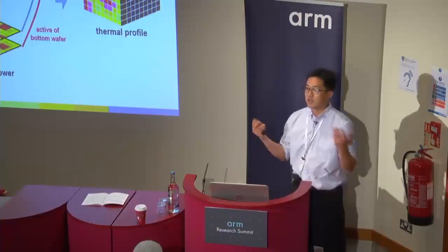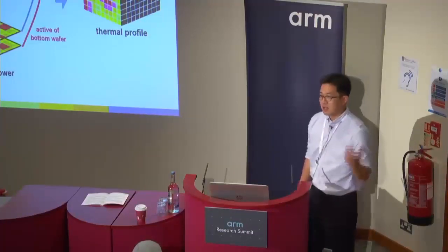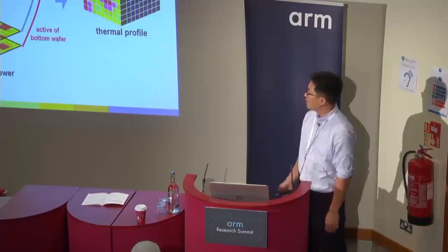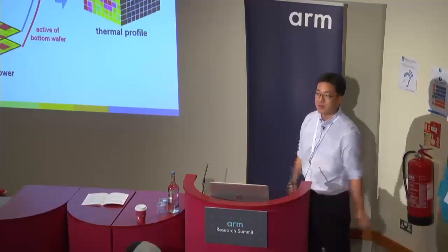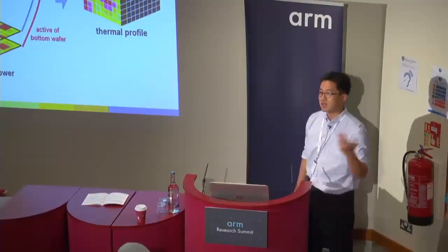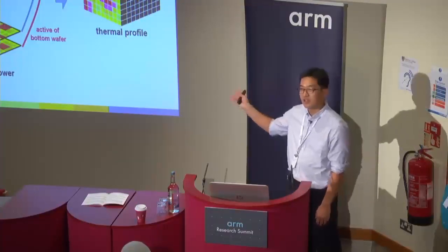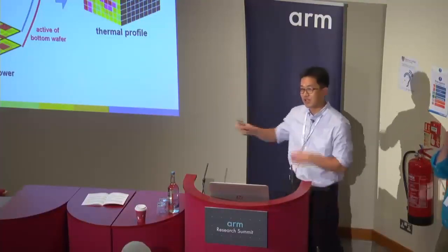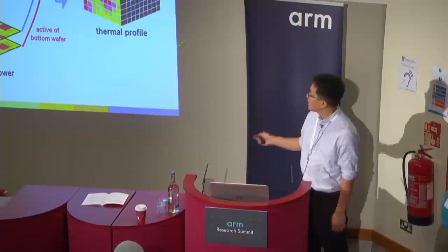So we just assume the switching activity of the flip-flops and primary inputs and outputs, and with that we calculate the cell power, and we can change that to anything you want. That is actually the advantage of our in-house tools. We can configure anything we want with these frameworks.